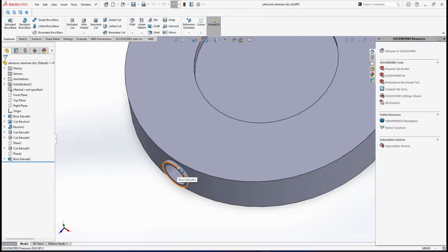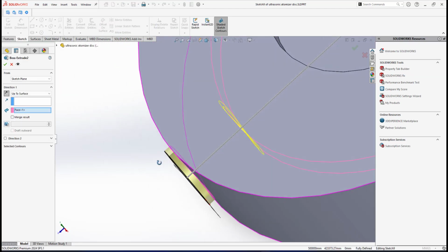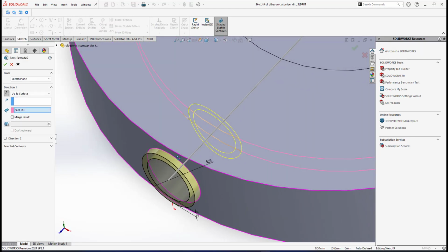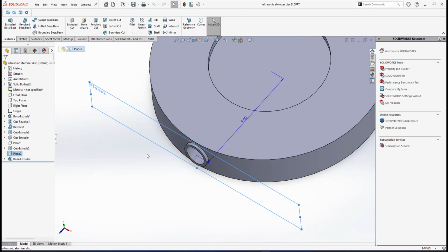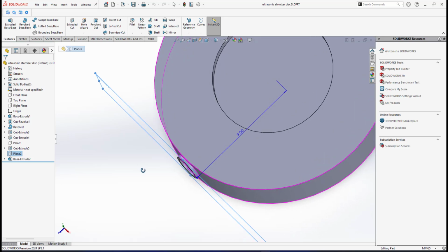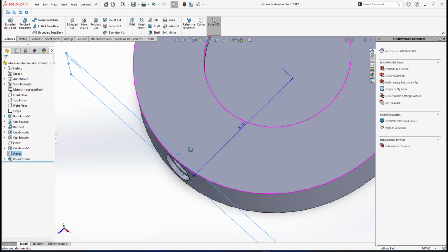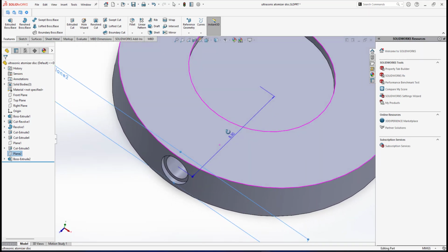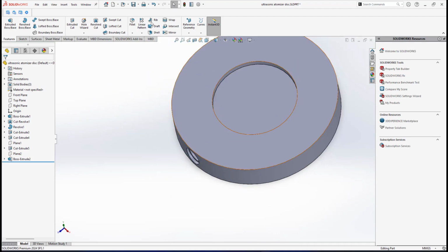So this boss is the last thing here. I cannot do it like that. So I will edit it, since I made it at this plane. So the plane that I'm extruding from will be this plane. I think this is too much, about 9. So if I go for 8.5, it needs to be a little bit inside that. 8.5. Okay, it's good. It's already adjusted to 8.5.